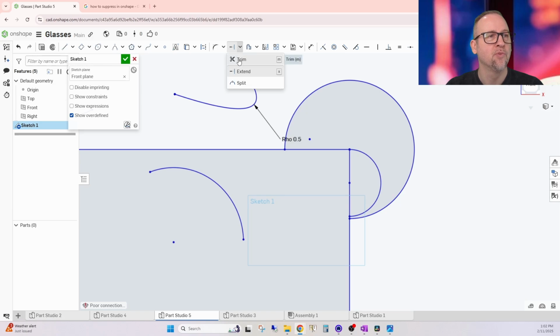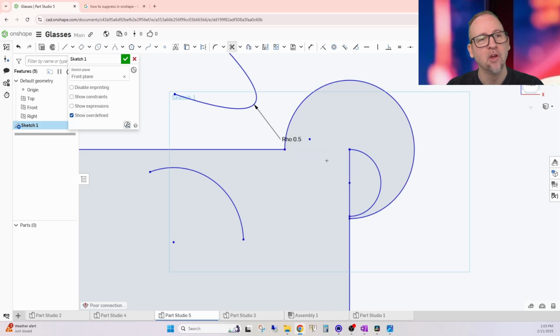So let's go to trim over here. Let's say this rectangular shape, I wanted to have like a Mickey Mouse ear on it. I could simply run it over here and it would delete these automatically. And if I wanted to have this back to an intersection, then we could just extend this guy to this guy and it does the extension. Then if we want to do it again, we can go to this guy, click on him, and pull it out, and that does the extend on that. Okay, so we'll click on that to unselect it now.